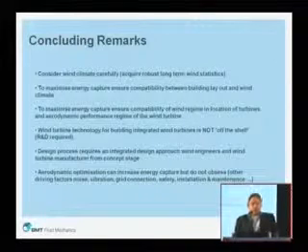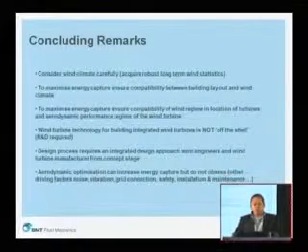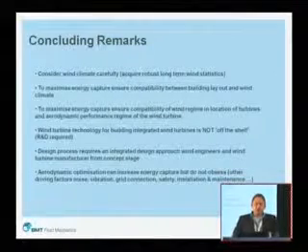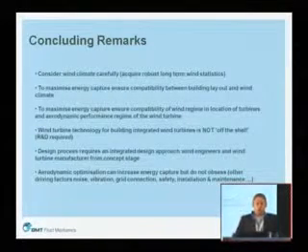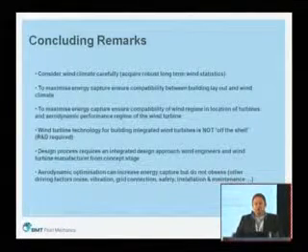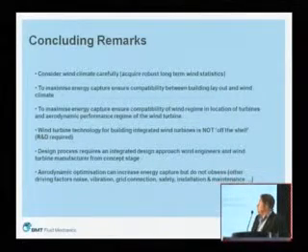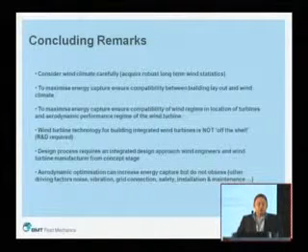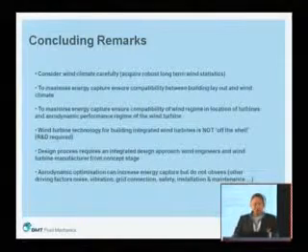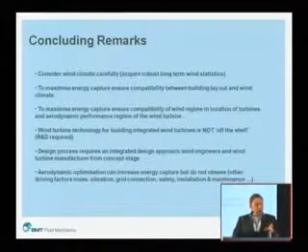So, really, if you are embarking on a project like this, you need to start off by considering the wind climate very carefully. Are you in the right sort of location to consider such a project? If it's not very windy on average, and you're not talking about storm events, it's unlikely that you're going to get much energy out of it. In your design arrangement, you need to ensure compatibility with wind climate and wind directionality and the building layout, i.e. building orientation.